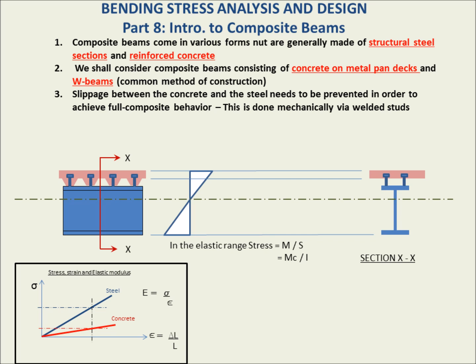Let's start by looking at the stress distribution following the strain distribution with the steel. So we see a linear distribution of stresses going from the tension zone into the compression zone, and we would expect it to continue in that manner shown here, the stress diagram, this straight line going up, if it was a homogeneous material.